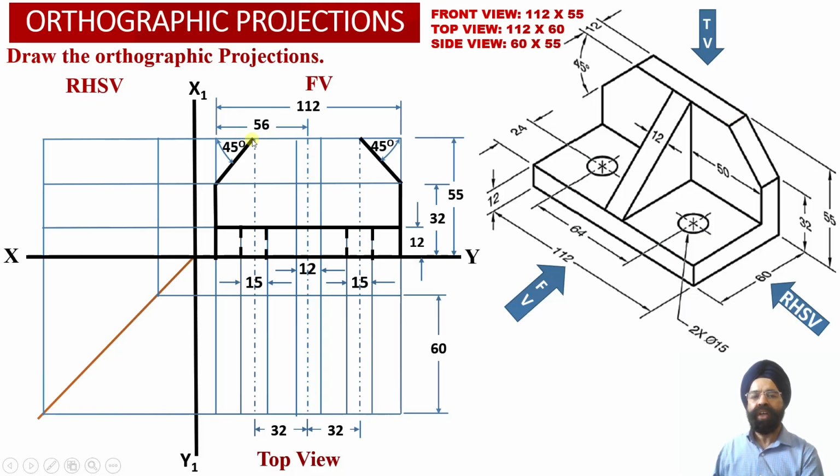now this remaining portion of the top surface we can join as a straight line, which is going to represent the front view projections corresponding to this rectangular surface over here. So this rectangular surface will be projected as an edge view into the front view projections over here. Another thing we will be witnessing in this particular case, that this inclined rectangular surface corresponding to element number 3, which we are going to obtain into the front view projections as apparent shape rectangular projections over here.